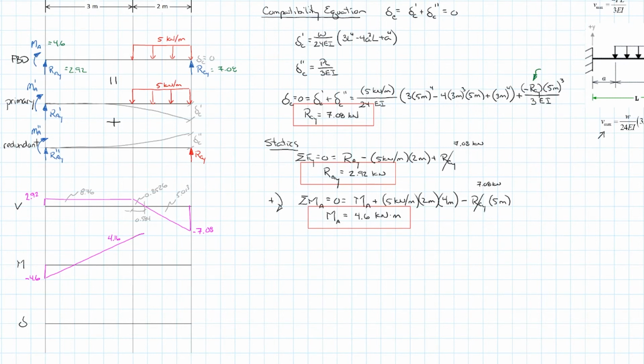And that's going to continue up, sloping down and getting to a zero slope at that nexus point there. And that value is 5.013. And then if we subtract the area of 5.013, that allows us to slope back down and come back to our endpoint here. And if I were to draw in our deflected shape, it's coming out and then it bends back up to our support.